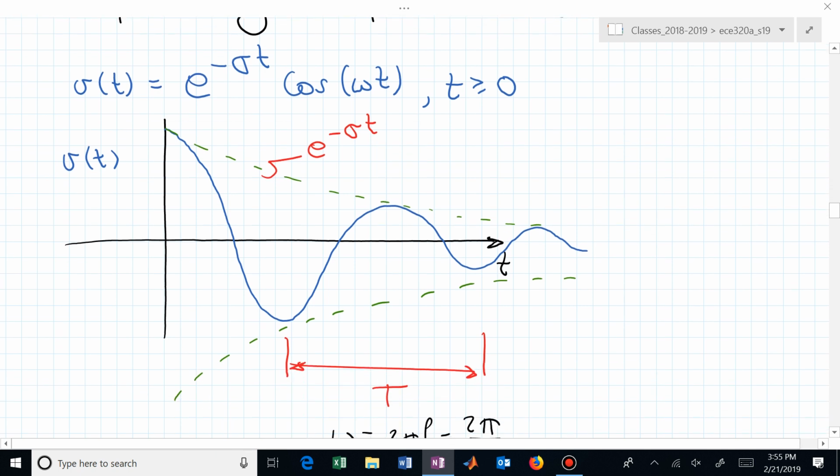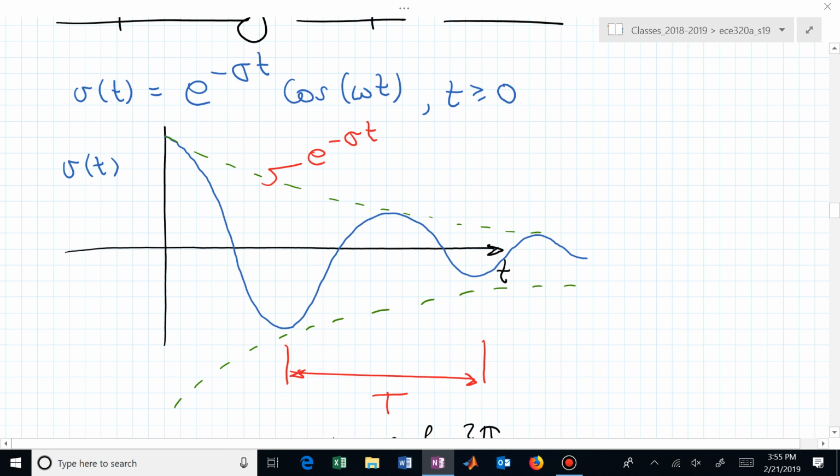Likewise, you could measure how fast this is bouncing back and forth. It's bouncing back and forth, but it's also decaying. But the bounce, so the distance between peaks or the distance between valleys, the distance between two similar points on that sinusoid tells us our period of that sinusoid. That now allows us to find omega. When you see this exponentially decaying or damped sine or cosine, I want you to be able to visually think about what that looks like. And that's the picture.